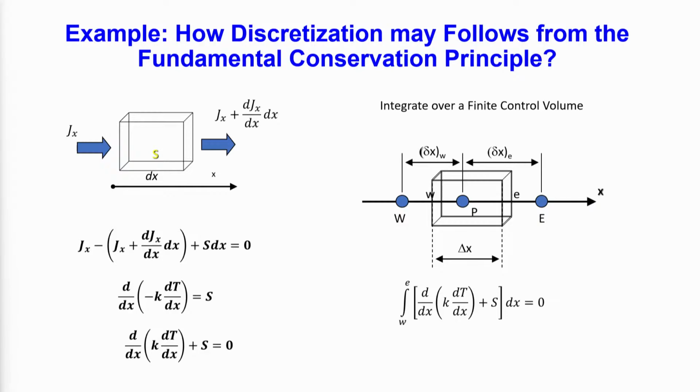The source term formulation takes the temperature at P, whatever it is, as the same throughout the control volume. That means a piecewise constant temperature. Piecewise constant temperature is a further simplification of the general linear variation. We will see whether that creates any problem or not, because otherwise it is quite simple to do in terms of the analysis.